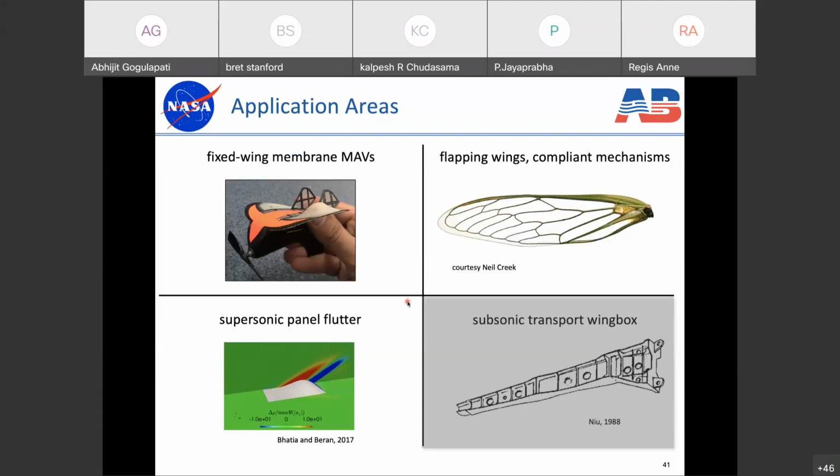And the reason we care about supersonic panels is because supersonic airplanes tend to have a relatively low aspect ratio with high sweep. The aeroelastic physics at the wing level are not that interesting because the wing doesn't deform much. But we can have panel flutter. All the ingredients are there for it, as we've seen in the previous chart.